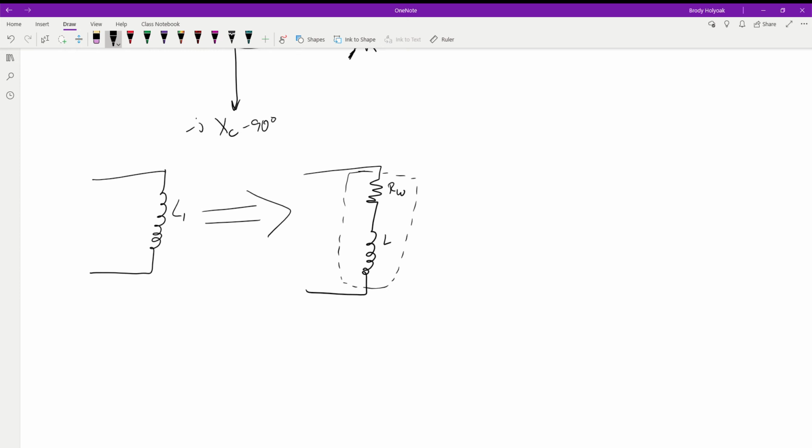So for example, at low frequencies, you're going to have a very low inductor or X of L value. So at a low frequency, low f, we're going to get an X of L value that is low. Now, how low? Depends. So let's say we're running at a frequency, we have an inductor in place, and our X of L is now only 15 ohms. Okay?